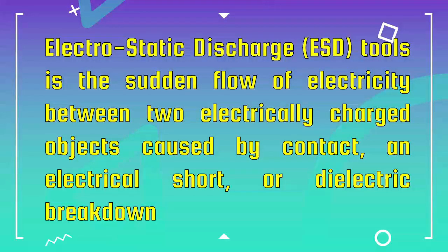This is the sudden flow of electricity between two electrically charged objects caused by contact, an electrical short, or dielectric breakdown. Like the shock you receive when rubbing your feet on the carpet and touching something metal, ESD can occur when working in your computer and can cause damage to components. ESD can occur without you feeling a shock and only occurs while working inside a computer or handling an expansion card or other hardware.